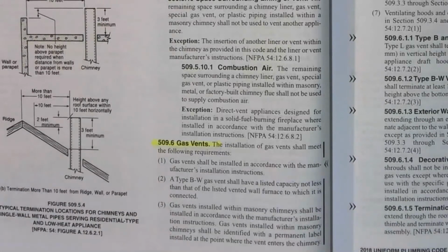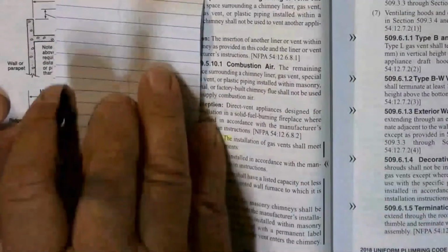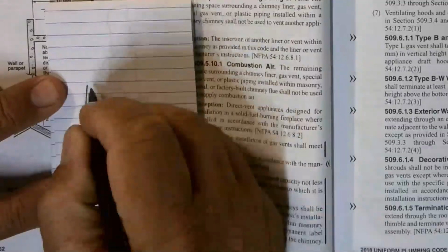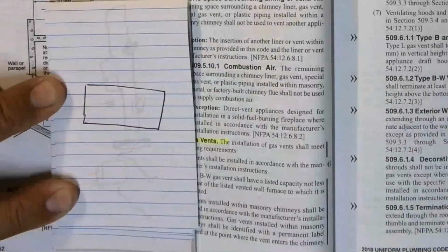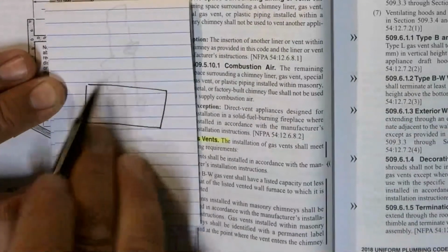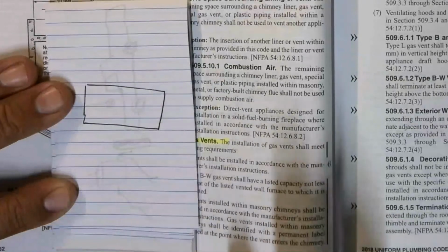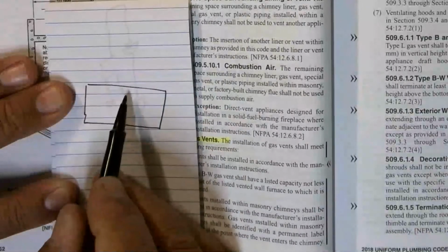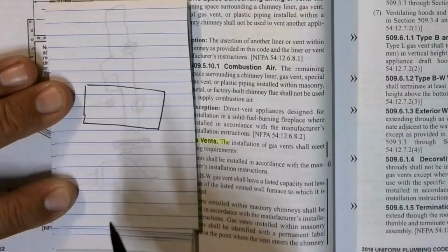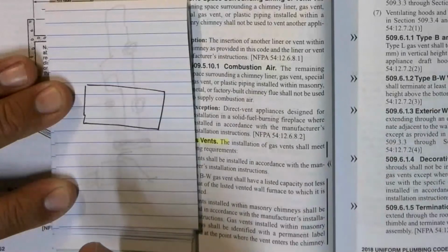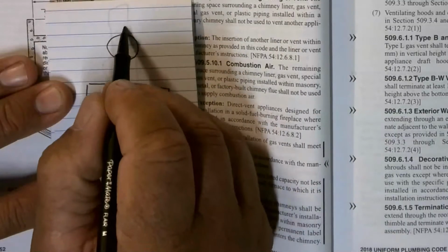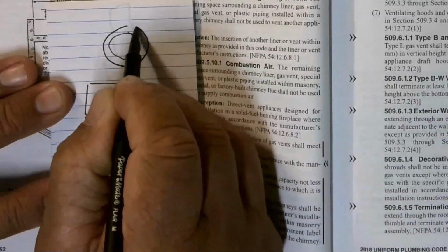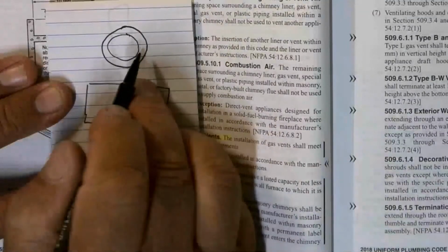So a BW gas vent. Let's say that's a stud bay. Okay, if I'm going to run a B vent through this stud bay, you know, most stud walls are what, 2x4? So how can I get like a 6-inch exhaust or a 4-inch exhaust on a B vent? A B vent looks like this. You have your exhaust, and then you have also another covering around it. And this is very similar in the direct vent